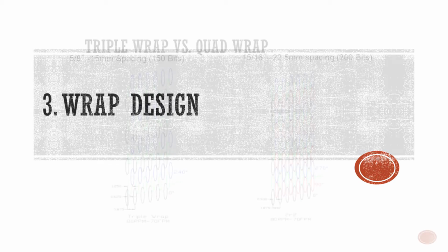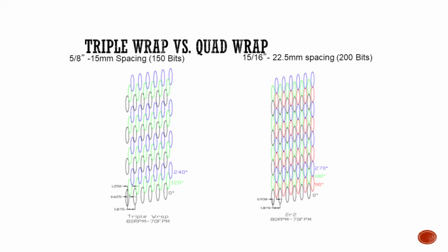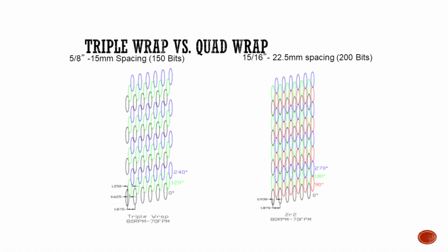The industry started with a double wrap years ago, in the late 70s, early 80s, and quickly moved to a triple wrap. The double wrap just had 2 coils around that drum, whereas a triple wrap has 3. That third wrap allowed them to produce around 50% faster and still hold the same pattern. Shortly thereafter and presently, we're seeing a lot of interest in 4-wrap drums.